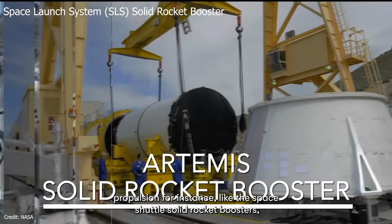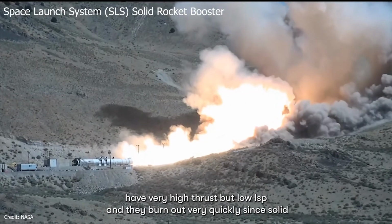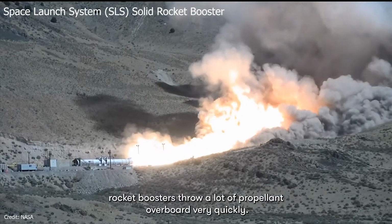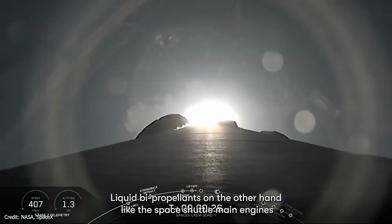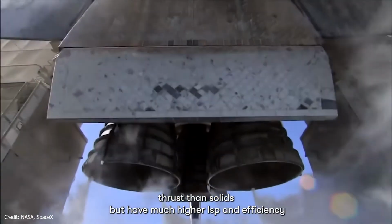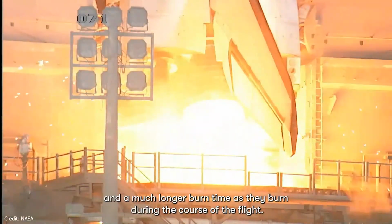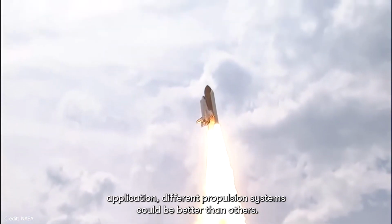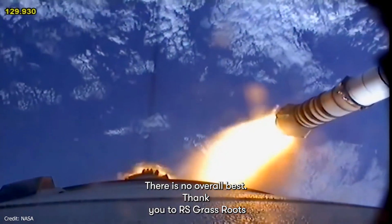Solid propulsion, for instance, like the space shuttle solid rocket boosters, have very high thrust but low ISP, and they burn out very quickly, since solid rocket boosters throw a lot of propellant overboard very quickly. Liquid bipropellants, on the other hand, like the space shuttle main engines, have a little bit lower thrust than solids, but have a much higher ISP and efficiency, and a much longer burn time as they burn during the course of the flight. And depending on the application, different propulsion systems could be better than others. There is no overall best.